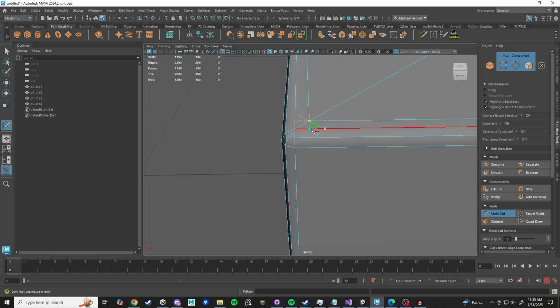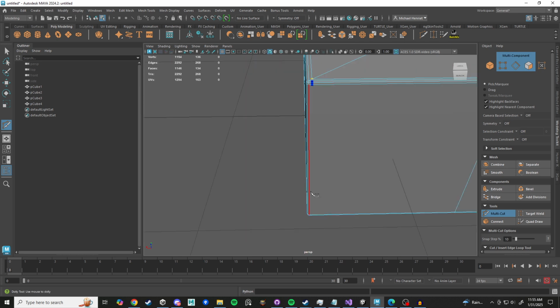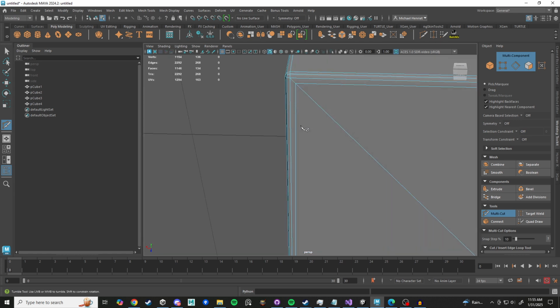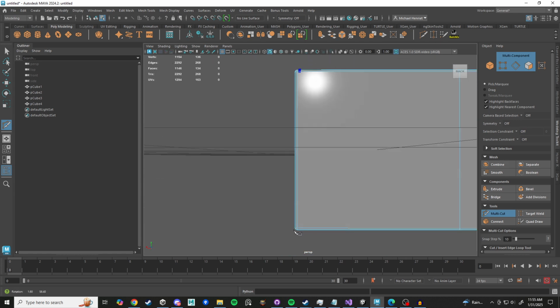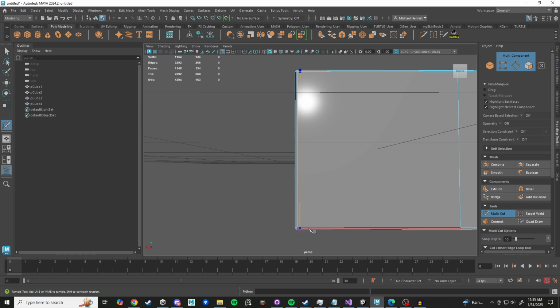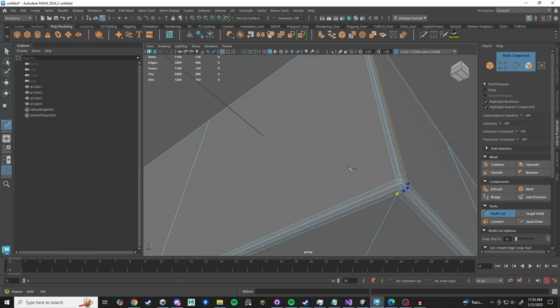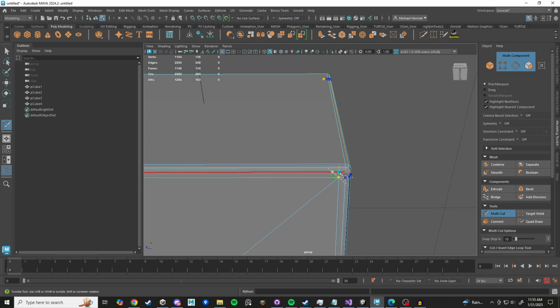If you're using multi-cut, you can use Control and Shift and cut, and that will give you a nice 90-degree angle from that last cut. Or it's going to try at least. Sometimes it doesn't go according to plan. But yeah, you can do that. And look, it gives you 45-degree options as well. But I'm going to go up this way.